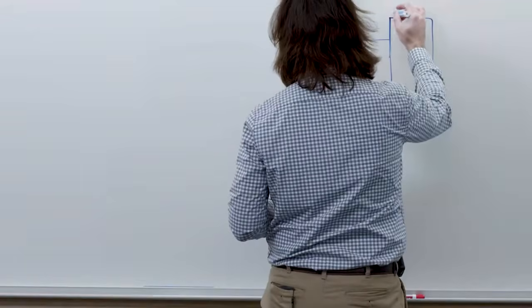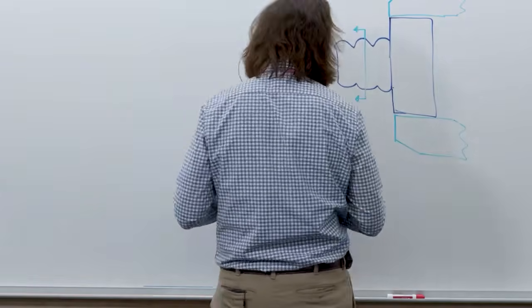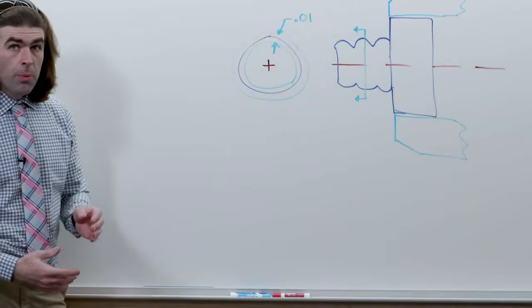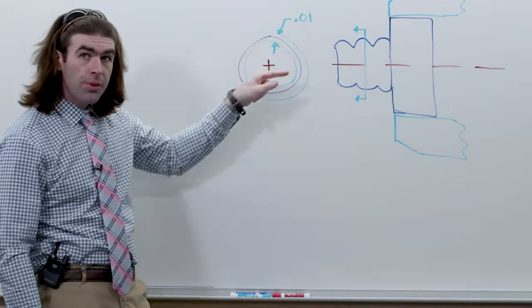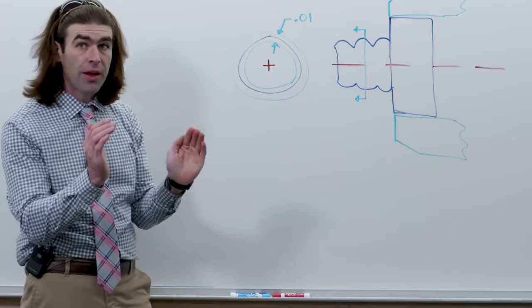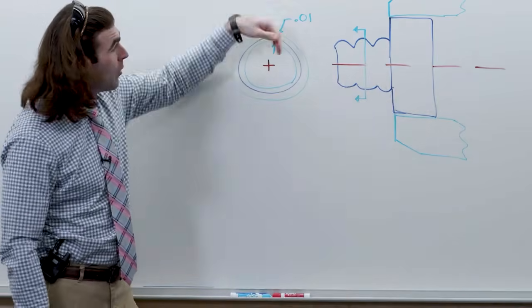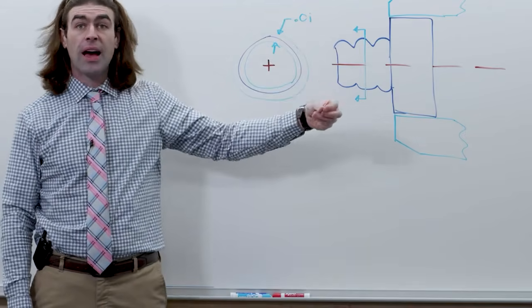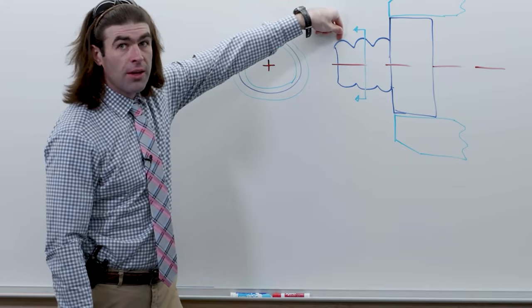So what that could give you is that if you check it here, right, or here, you could get something that's within the runout tolerance, so relatively circular and located to the datum axis. But along the length of the part, it could vary within the size tolerance, right? So you check here, it's circular and located.